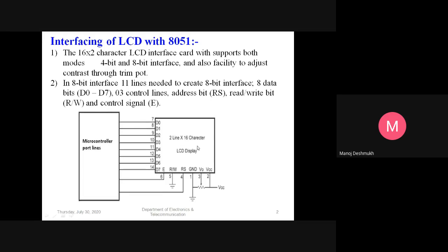Whenever we turn on the LCD, or if you are looking at the LCD display of some devices, it illuminates a yellow background color. This yellow color is nothing but the backlight illumination color of an LED. So pin number 15 and 16 are for the illumination of the backlight LED. If you do not want to illuminate the backlight LED, you simply neglect these two pins.